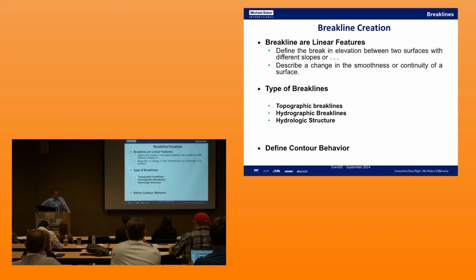So this is one of the very critical components in any project planning. Ultimately you should know the purpose of the product, and accordingly capture the breaklines. And the last point is, the breaklines along with the ground points define the contour behavior.